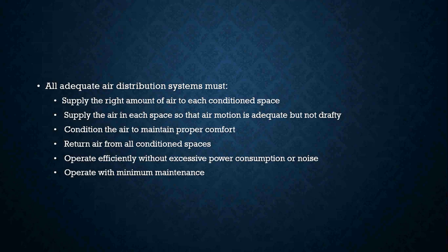Your return air for all your conditioned space, that just comes down to ductwork design. Is the return air ductwork adequately sized to move the correct amount of air through the air handler and all that stuff? Operate efficiently without excess power consumption or noise. Well, that's just simply looking at the unit and making sure that everything is the way it's supposed to be. Okay, operate with minimum